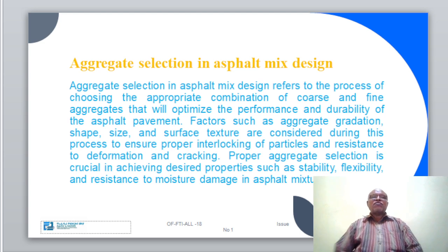To design an effective asphalt mix, several factors related to aggregates need to be considered. This includes the gradation of the aggregate, which refers to the distribution of particle size within the mix, and a well-graded aggregate blend ensures proper compaction and stability of the mix.